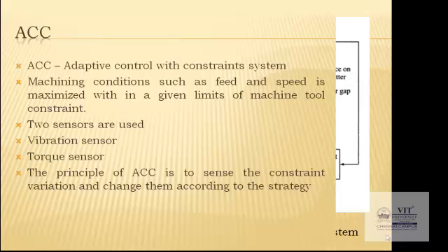In those cases, if it is a spherical face tool, that is a ball end cutter, it is very difficult to measure the tool wear rate. Okay, because the depth of cut is almost very less, and also the tool wear rate you can't predict at all. So in those cases, what you can do is, what will be the maximum value or what will be the constraints that are given. For that particular constraint, you have to set all the parameters.